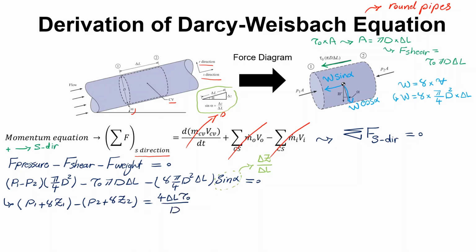All right. This equation is based on reorganization of the force equilibrium that I've written for you. The reason that I have written this equation like this is because I already know these terms, right? These terms represent piezometric pressure at section 1 and piezometric pressure at section 2, right? And I know, based on the previous slide, that piezometric pressure at section 1 minus piezometric pressure at section 2 represents gamma times HF, gamma times head loss, right?